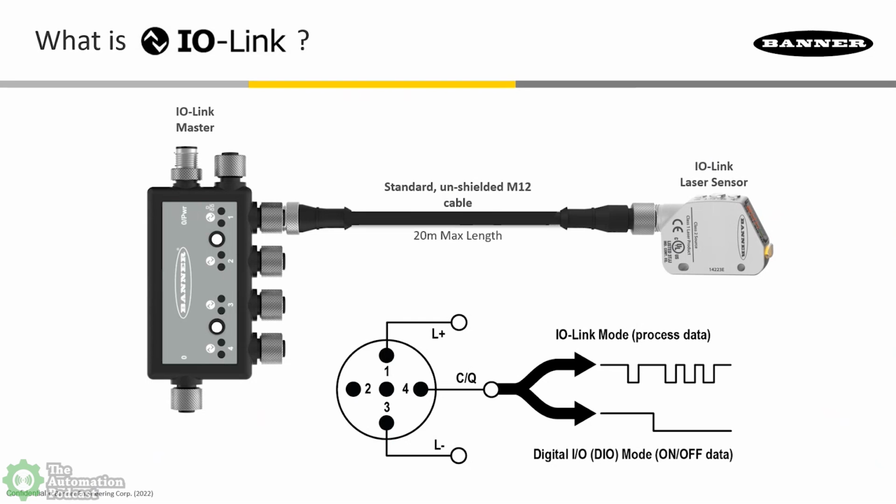If we look at applications throughout history, at all the discrete I/O and traditional I/O systems, and simplify a traditional discrete I/O point that's been used for years and years, inputs just measure if voltage is present, and outputs trigger an external action via a PLC or some sort of controller.